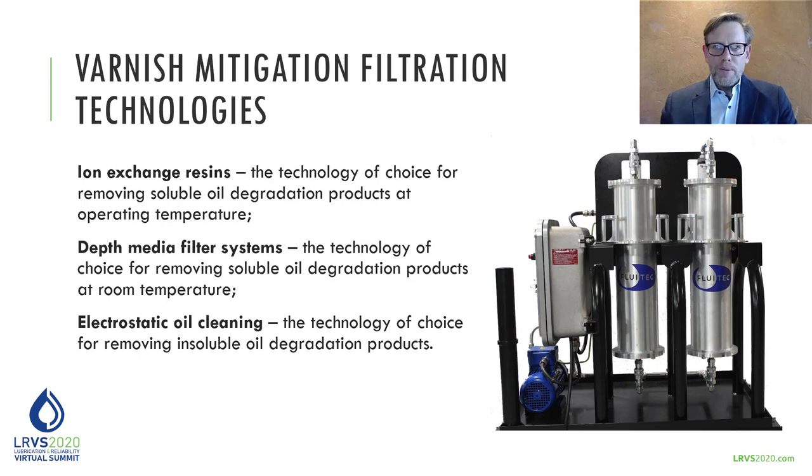Let's talk a little bit about solutions. The most important thing is we need to be actually testing, measuring, and monitoring varnish potential in the fluid. What happens, how do you actually manage this now that you have a high varnish potential?